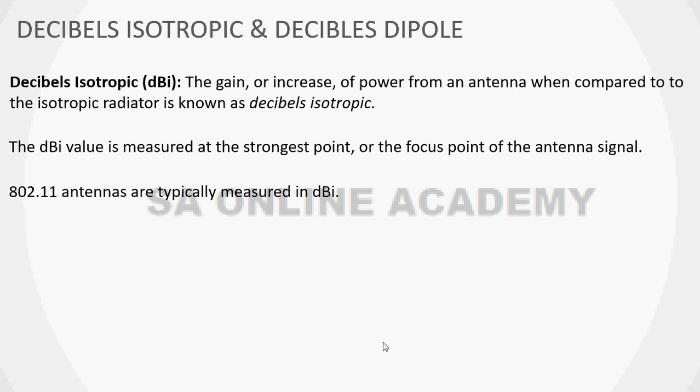Antennas are typically measured in dBi, and transmit or receive power will be measured in dBm only. You will find this throughout Wi-Fi and throughout these videos. Very rarely are other measurement units used, whether relative or actual. Only two are majorly used: dBm, which is the actual unit of power, and dBi, which is a relative unit of comparison.